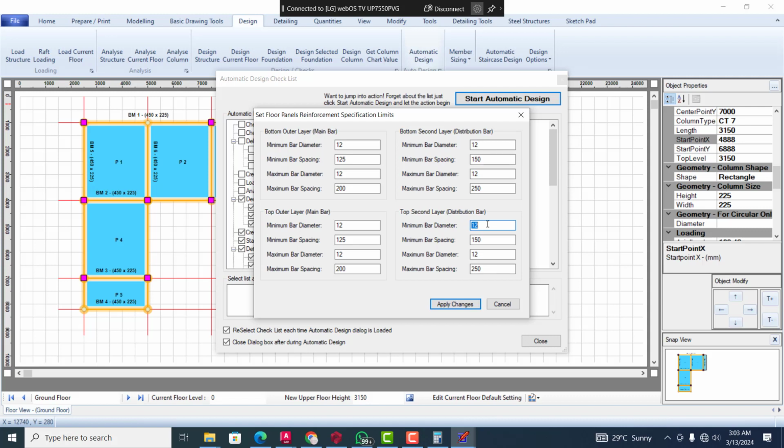This is going to be 10. Now, what this one is telling us is the reinforcement that comes back. You know, there is a reinforcement that comes back inside along an external beam. That reinforcement that comes back inside, it will dangle like this. You need to provide a reinforcement at the top.